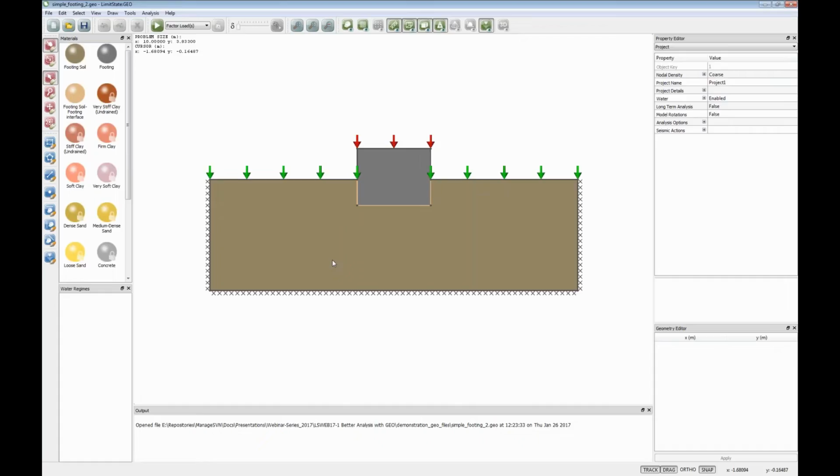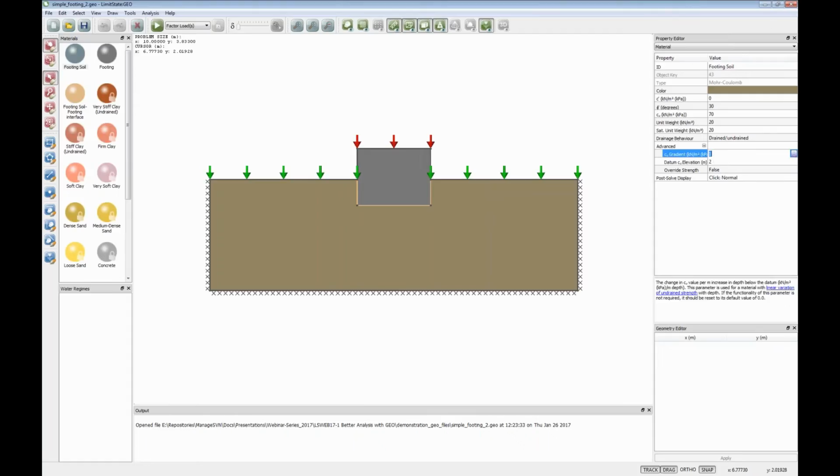So here we've got a slight added complication in that we've got a buried footing. Now there are ways of using Terzaghi's formula to deal with that, but if you want to account for the strength here and here, it becomes slightly unsatisfactory to start using depth factors. We can also, in this model, I've actually set it up to model a gradient in strength. So we've got an undrained soil, and I said that the strength of the soil is increasing by 1 kPa per meter depth here.